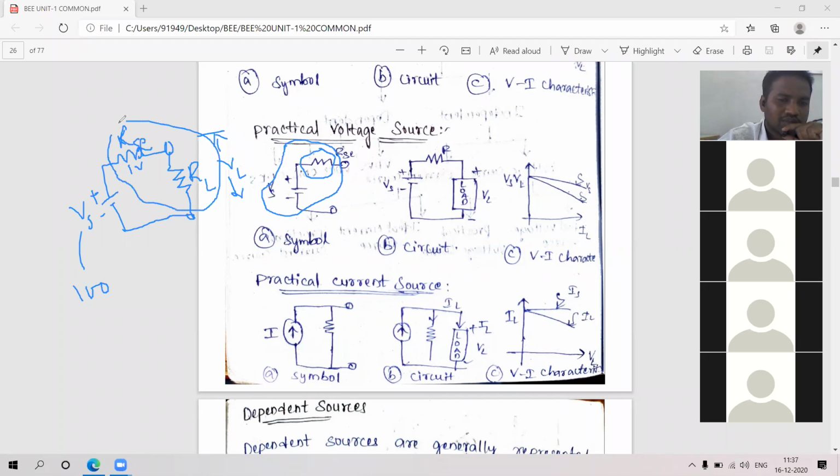These two are drops, the resistor and the load, passive elements, meaning voltage drops take place. V_S is the voltage rise, indicated with plus, and the voltage drop is indicated with minus 1 volt, and the load drop is minus V_L. So the sum of all voltages in a closed circuit is zero: minus V_L equals minus 99, the minus signs cancel, and we get V_L equal to 99 volts. So 99 volts we are going to get at this load.